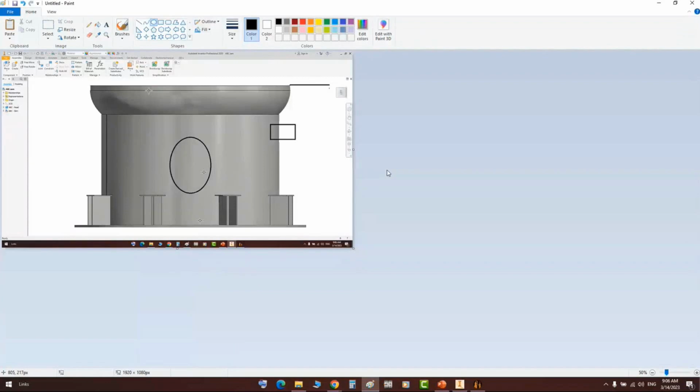Let's imagine that we have a shell here. If you add a shell here after this head, this shell takes the same information of the skirt: the same skirt inside diameter, the same skirt thickness. So at the end of this head, you will create an element with the same information as the skirt course.